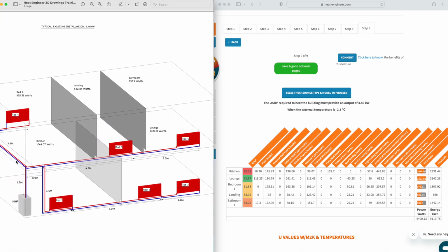And obviously, you could have another drop there, you could have another T-piece coming off of there for some rads over this side or whatever it is, and you just name it. So that might be circuit A, that will then be B, and then C and D and E and F and whatever it is. And obviously with the alphabet you've got up to 26 circuits, but we can start labeling them all sorts of things. It could be Z25/B or something like that, if that's how you wanted to do it, and you've got loads of different sections.